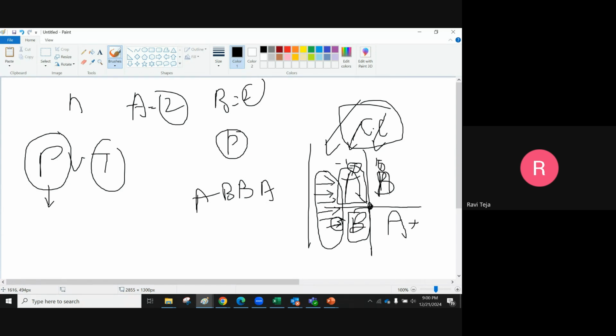Imagine if I put A here and B here, in the other case, if my etching is from the top, then A is affected more compared to B. There might be some difference from A compared to B. So to avoid this, we make this common centroid for all the devices.